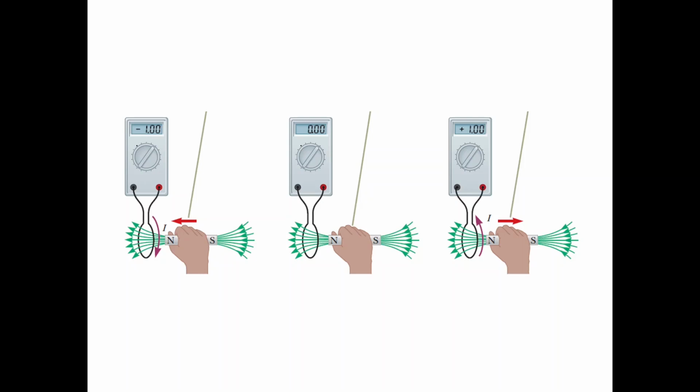Because if we want to measure current, we don't want to interfere with the electric circuit which we want to measure. So we need to connect in series. And in that case, the internal resistance of the device, in order to have minimum impact on the measured current, should be very small. In opposite, if we measure voltage, the connection is in parallel, and we want to make sure that there's minimum current flowing through the voltmeter in order to show the correct voltage drop over the part of the circuit. So that is important.